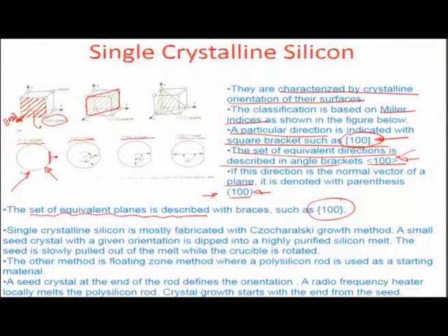So, there are a couple of other methods which are also used. Czochralski's I already mentioned. So, there is a floating zone method where you do not have any thermal gradients anymore, because in the floating zone method, the polysilicon material is uniformly heated through radio frequency means, so that there are no thermal gradients, and therefore, float zone methods can result in even higher purity in terms of the structure etcetera of the silicon.